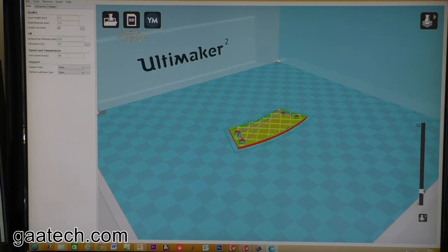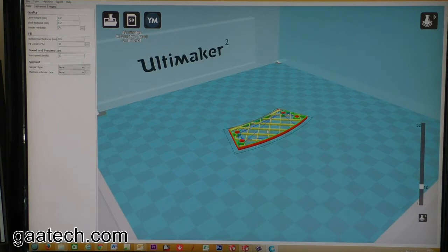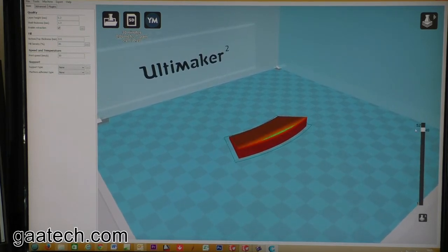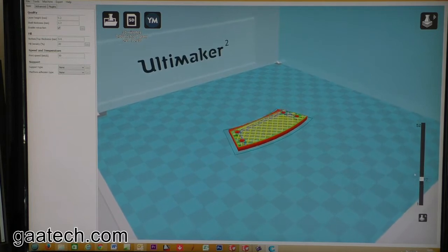As the print builds up you can see in the middle of the print all the infill coming in. So that was 10%. In the video that you're going to see it's 20%. So if you change that to 20%, you can now see the grid becomes more dense, and that's just going to make the print stronger. So this just gives you an idea of how your print's going to be made. Very useful.